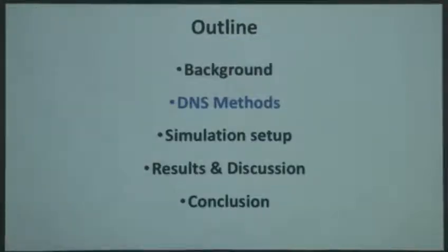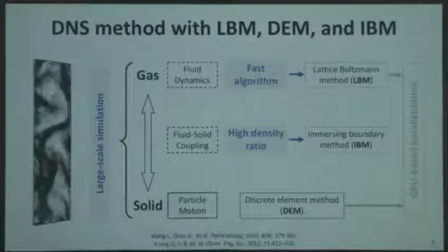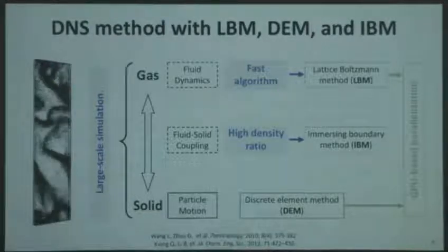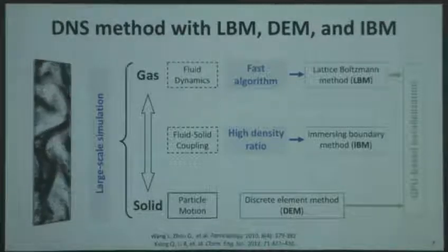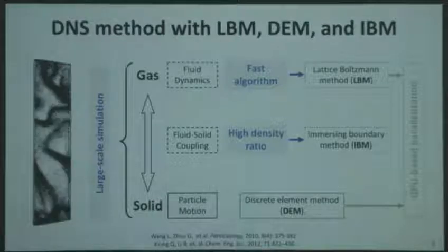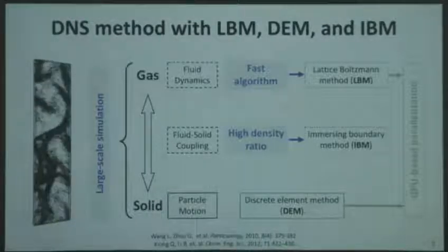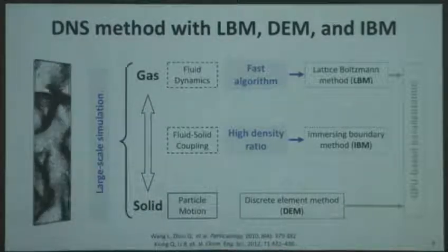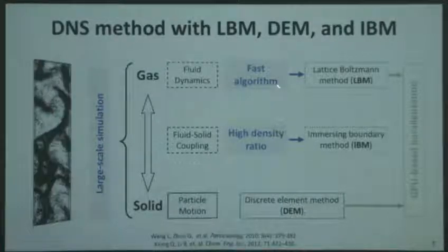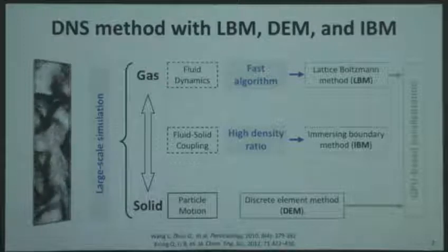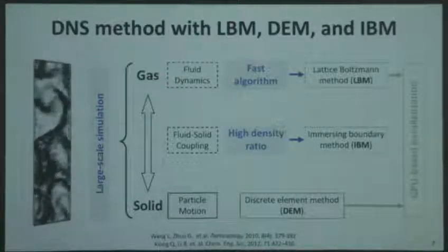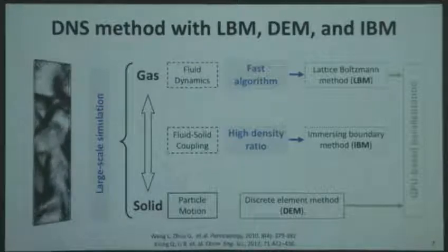So then to the DNS method we are using now, we actually mainly using two varieties. One is the gas phase is based on LBM because it's a very fast and explicit method, and the solid phase is on DEM. And both the gas phase and the solid phase can make use of GPU computing for scaling up. For go to larger scales,